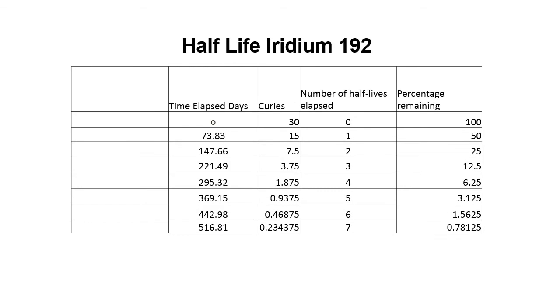So here's the half-life of Iridium 192, which is 73.83 days. So you can see it decays pretty quick. You start out with 1 pound of it, and within 2 years, you're down to almost nothing left. So if you're going to shoot with this stuff, you're not buying this as a long-term investment. This radiation source is pretty short-lived. So you just have to keep that in mind. But that's what they're talking about when they talk about half-lives.